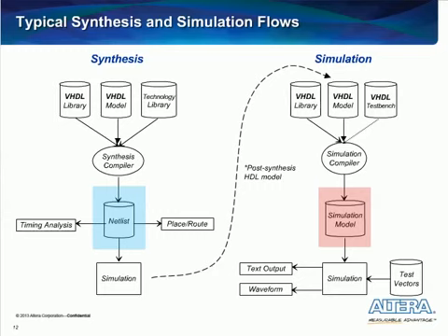If post-synthesis simulation is desired, the synthesis tool can produce a VHDL output file that represents the synthesized results. This can be taken back to the simulation tool and resimulated. This provides a check to ensure that the synthesis did not produce any errors.